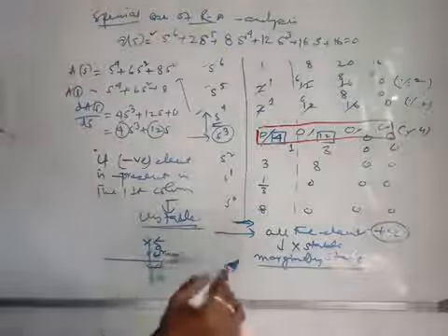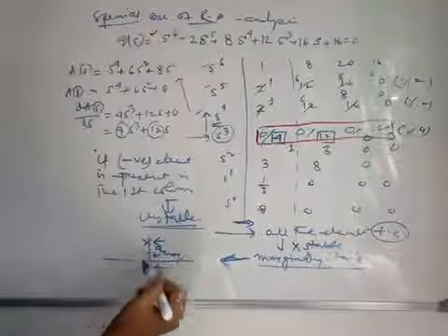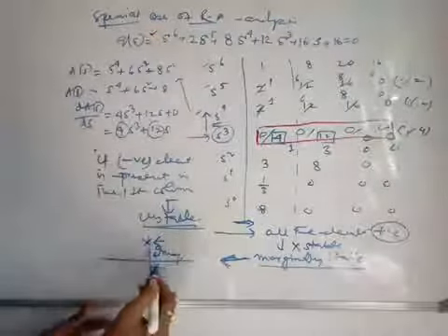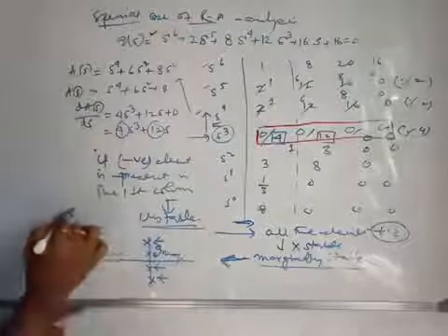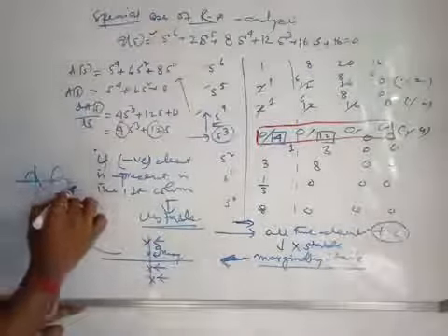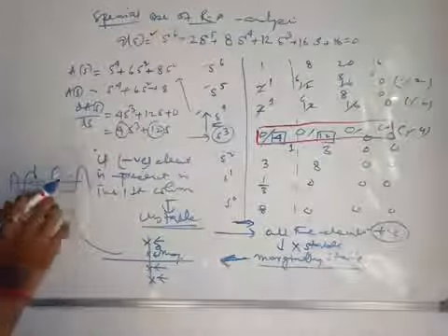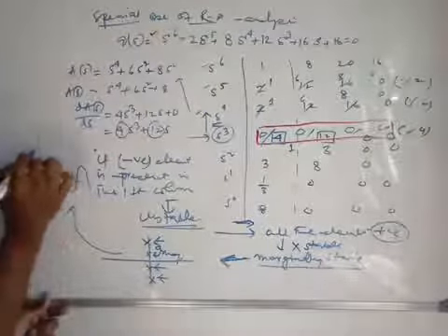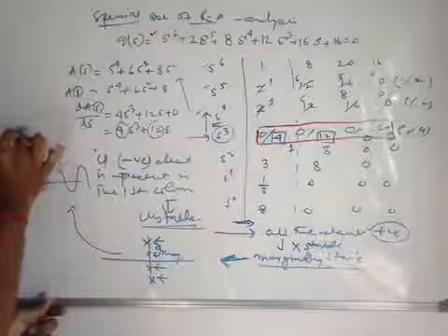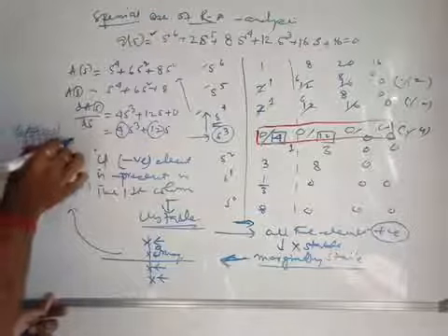So here also we will find some poles lying on the imaginary axis, and once poles are lying on the imaginary axis, what happens? The system's nature will be oscillatory, which is known as the condition of sustained oscillations, right? This is the condition for sustained oscillation.